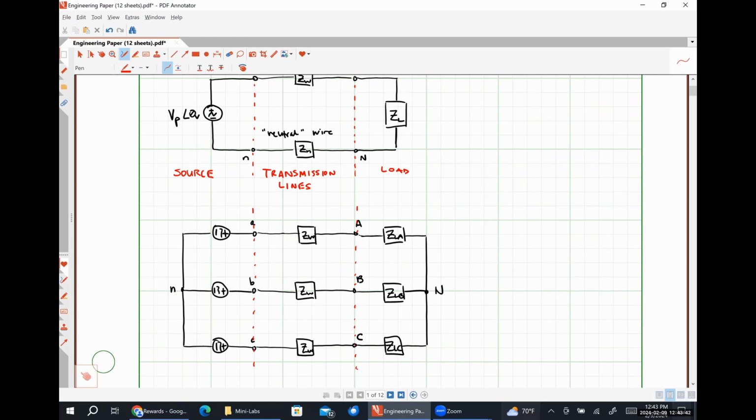So the reason why we typically use very, very high voltages when we're transmitting three-phase power is to minimize the losses, but that doesn't answer the question that I'm looking for, right? That's regarding minimizing resistive losses in our cables. Effectively, the higher the voltage that we have, the smaller the current that we will have. And so we will have smaller, what are called I squared R losses, which is literally just our conductors heating up because they're carrying current. So if we can get the system to carry less current but the same amount of power, which is what transformers do, then we can minimize our I squared R losses by just boosting the voltage really high.